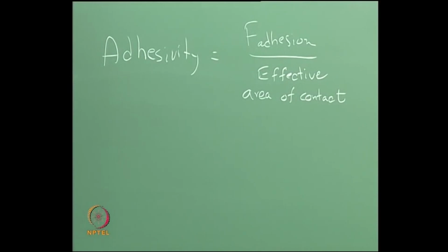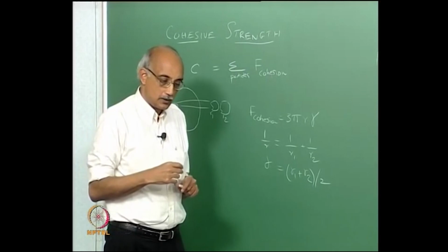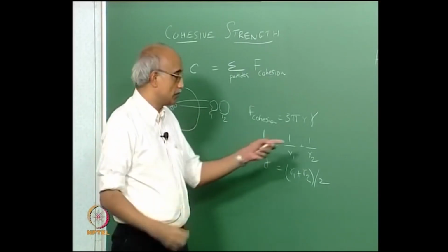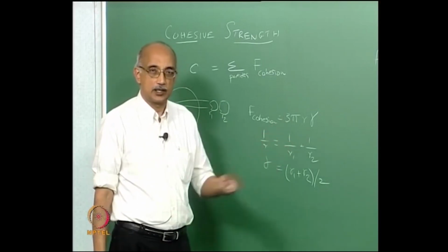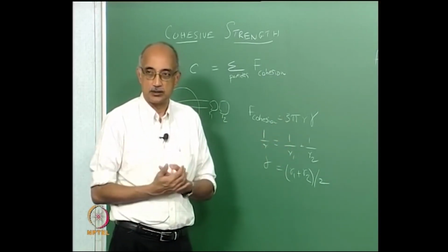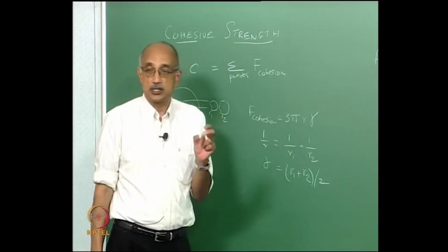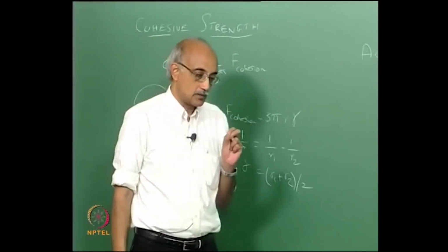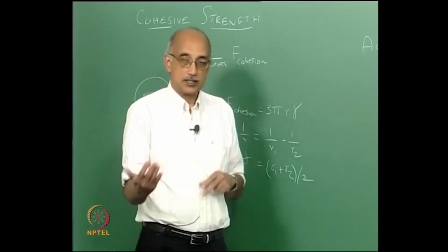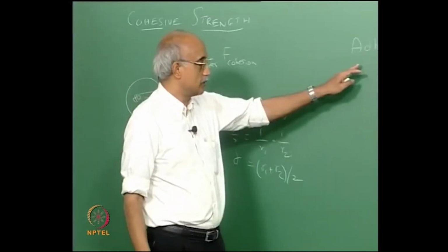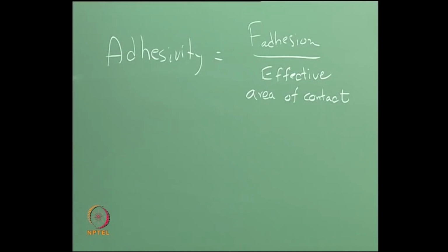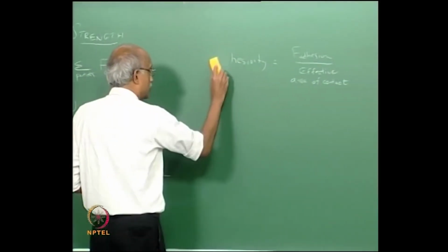Now, if you look at this equation, something that you might find puzzling is we have always said that cohesion, the cohesive force increases as particles become smaller. But if you look at this equation, r is actually in the numerator, right? So, that again is an apparent contradiction. This would say that as particles get larger, they are more cohesive. The reason is that when we say that particle size has an inverse effect on cohesion, what we are really talking about is this cohesivity or adhesivity parameter. Actually, in this context, it is known as cohesivity.